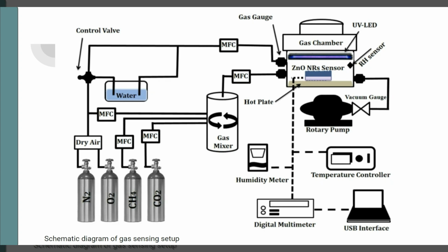To eliminate the disturbances or noise created in the output by these gas interactions with our sensing layer, we put in a UV LED. Why UV LED? In the dark and in the presence of UV, those gases give very little response with the sensing layer. So we use UV LED to eliminate those disturbances.